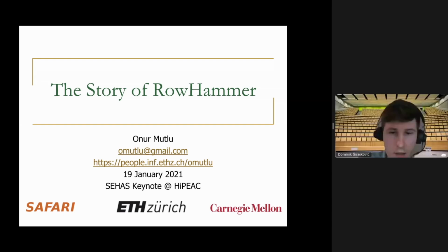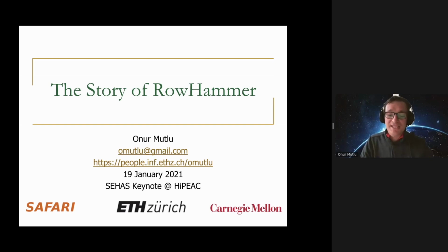Thank you. And from the same person, another question. On what levels can the PARA mitigation be implemented? Only BIOS? So that's a good question. Basically, when we envisioned this, it was not BIOS. It was basically online in the memory controller. So you could actually do it completely transparently to the user, programmer, any kind of software in the memory controller. And that's, I believe, the best thing to do.